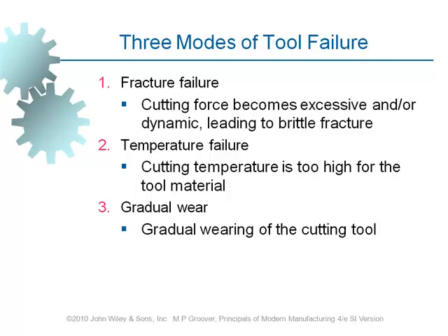Indeed, the first two modes of failure, which are fracture failure and temperature failure, are referred to as premature failures, meaning that the cutting tool can still last for some time if it doesn't fail. But we make the cutting tool fail because we have not used it properly. We are lowering the tool life of the cutting tool and making it necessary to replace it. By doing this, we are increasing the cost of tooling, which isn't desirable.